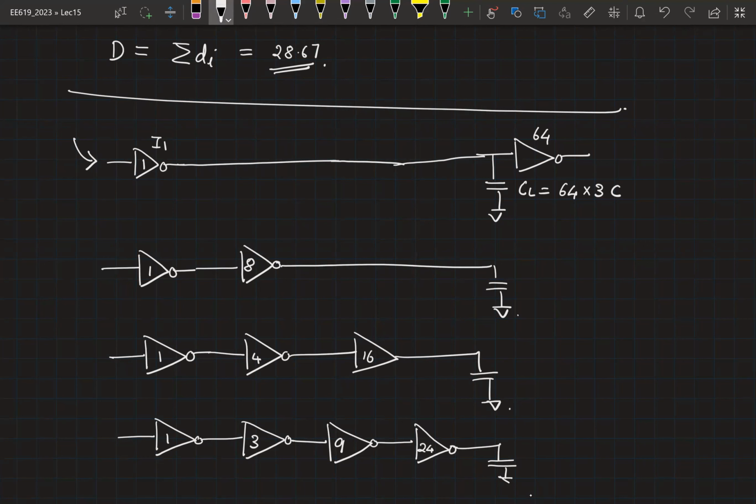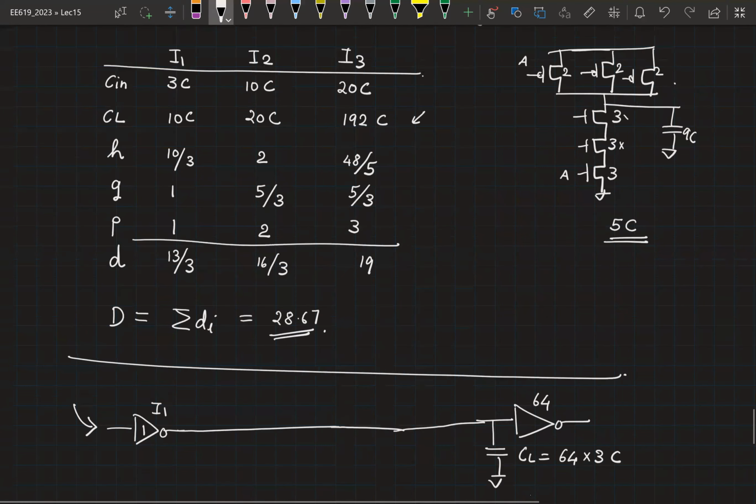Second one's output is, the load is still the same. So don't worry about the logical inversion. Assume that you can still correct for the logic at a later stage. But this is actually a very common problem that we have to do in digital designs. We'll need to route a clock for very long distances. It will see very large capacitances. And you are usually okay with adding as many inverters or buffers in the path as required. So can you calculate the delay for all 4 cases? And then let's see what inferences you can make. And you can also ask me if something about this calculation was not clear.